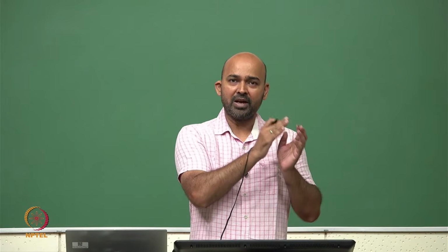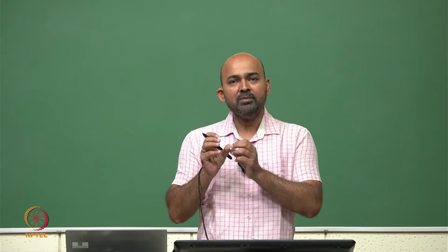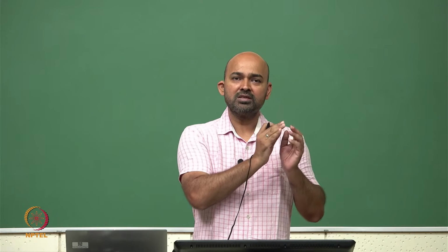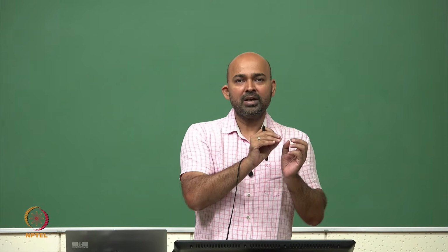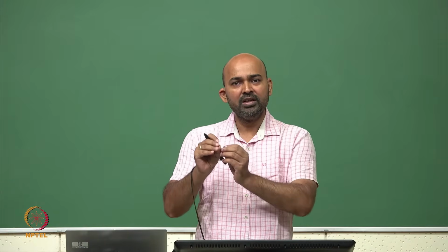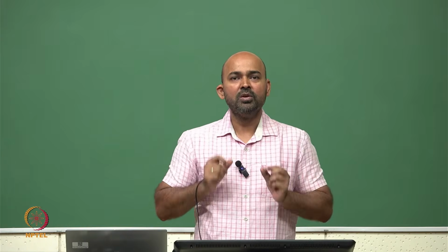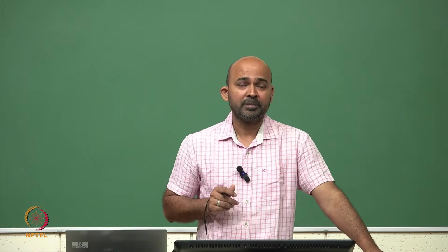For example, minus 40 is the starting point and we choose V increment as 1 degree. SPICE simulates the circuit at minus 40 degree and the next at minus 39 degree, then minus 38, and this is how it increases to 0 degree, then 1 degree, 2 degree, 3 degree. So, the increment between these two temperature values is 1 degree, which we can specify here.